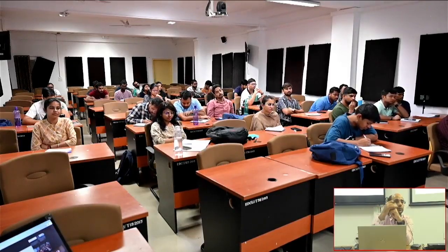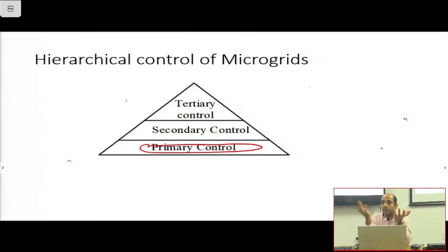If so happens, then the difference of frequencies will lead to an angular difference, and that angular difference will push power, okay, and that power will flow due to EV by X sine delta. So now the bottom source is pushing power. Then what is the choice left with the top source? The choice is that, well, there is more power coming, I have to reduce my power. So they will come back and they will manage such that they share the power equally, right?